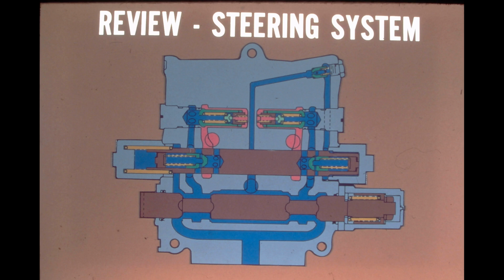Number 4 is false. The system relief valve is adjusted by changing the tension on the pilot poppet spring. And number 5 is false. Part of the return flow is sent to the oil cooler.